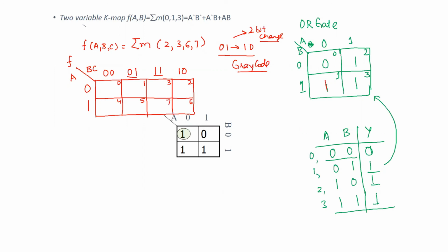I always tell my students to take care of this. Whenever they are going to fill in the values, the first prerequisite is to number the cells, so that it becomes quite easy to fill the values directly onto the K-map. Otherwise, it is going to be very difficult. You might end up with wrong or incorrect information being filled in.